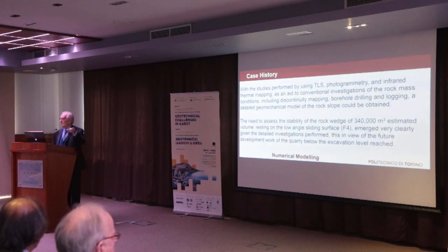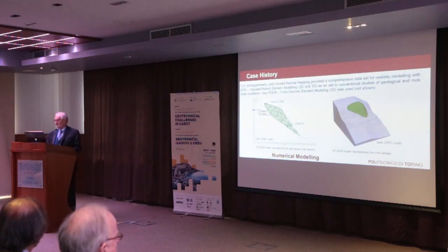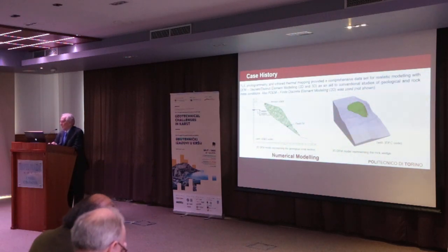What are the strategies that you are going to use? Are you going to remove this rock volume completely, or are you just going to reshape it, but monitor it continuously, very carefully? And again, we have novel techniques which allow you to monitor today. We have, of course, total stations. We have ground-based techniques which allow us to do this. But what you need to do, first of all, is to assess the stability conditions.